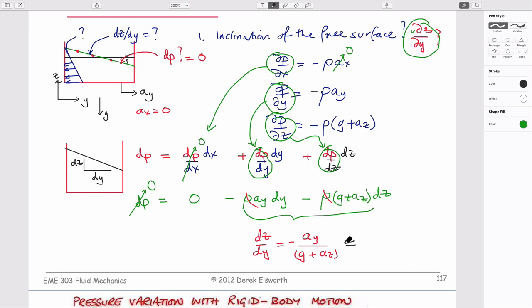Maybe it went to half of that. I would say this was maybe 1 to 2. And so if this is acceleration due to gravity, which is 9.81 meters per second squared, plus acceleration in the z direction. Well, the bus was pretty much going on a horizontal road, so there is no acceleration in the z direction. And therefore, the amount that must be on the top must be something like 4.9. Just because of this, right?